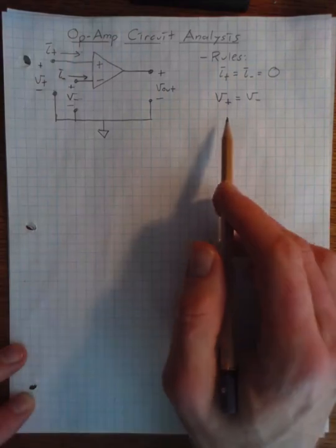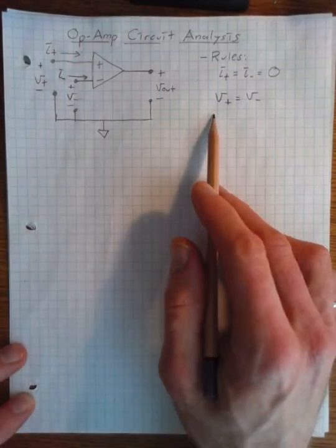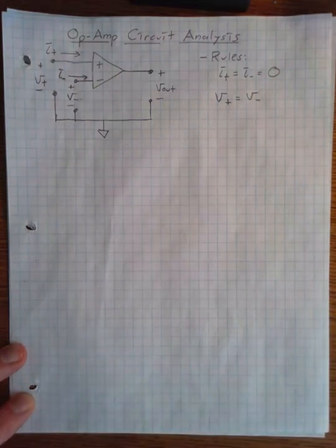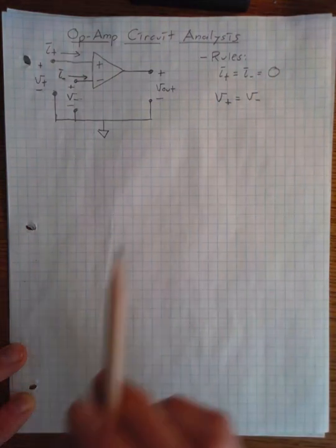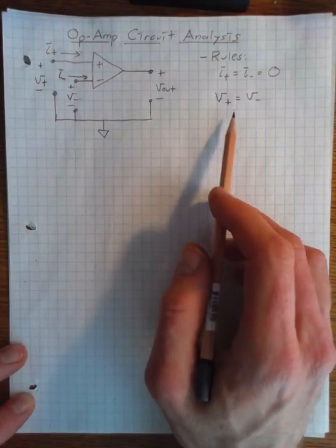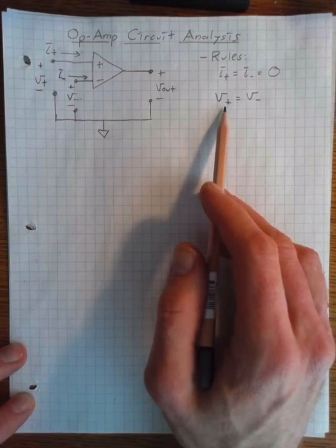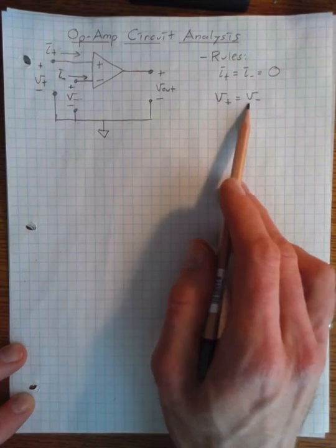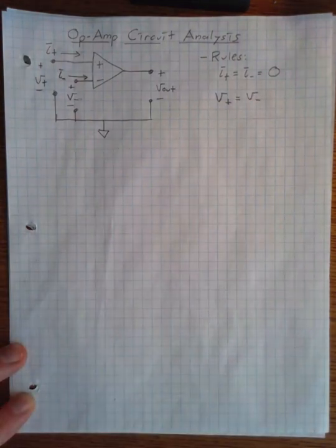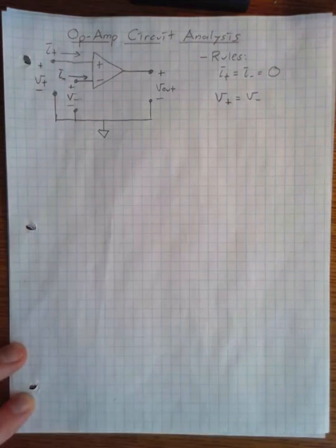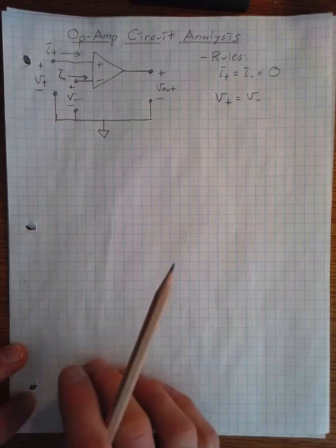And if you're curious about where this comes from, and you should be, I think, watch my later video in the Circuits 2 series about OpAmps. In particular, this was always a big misconception for me as I was learning circuits. I always thought that there was something going on inside this little triangle that forced these two voltages to be the same. And it turns out that that's not the case at all. This is a result of hooking up the OpAmp in a feedback configuration. And I'll talk more about that in the other lecture.